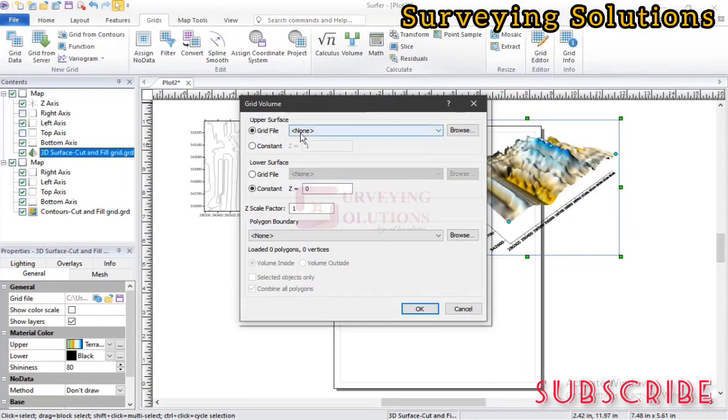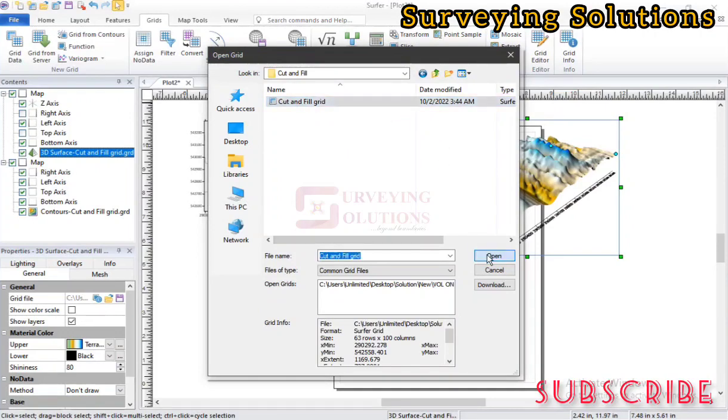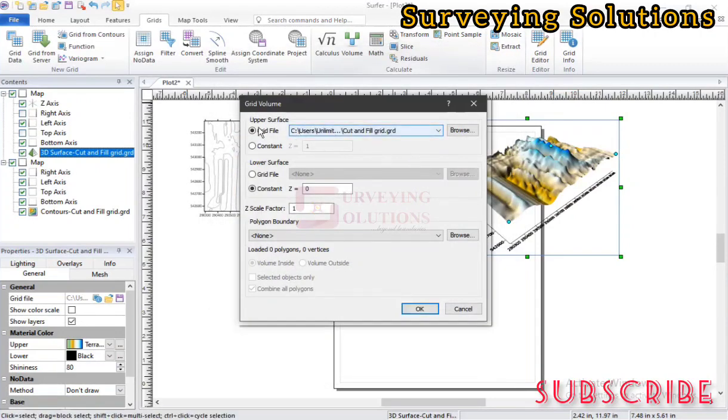Good. Now the first surface, definitely you can click on this because we already have two grid files on our map window. You can click on this and either select your contour or 3D surface cut and fill, or you click on browse to navigate to the folder it is saved in, right? Good. So we have the cut and fill grid here. Just open. Good. So that's the upper surface.